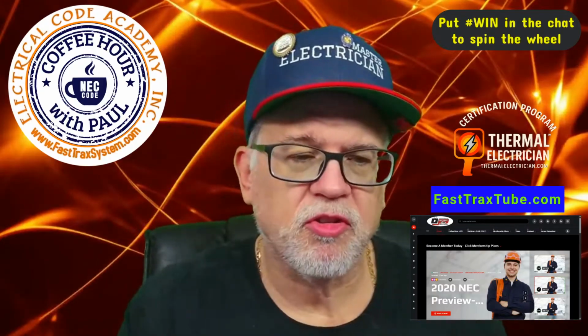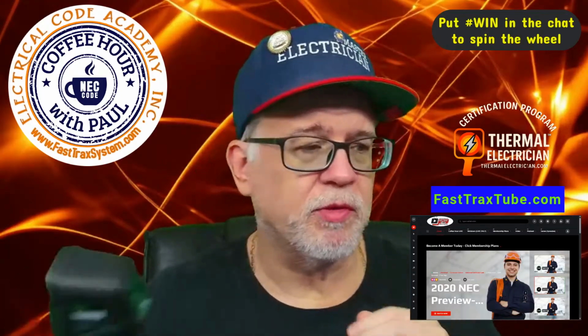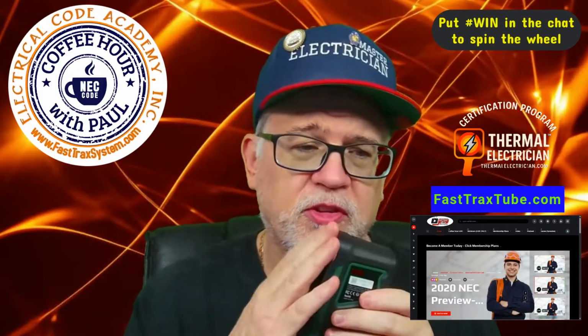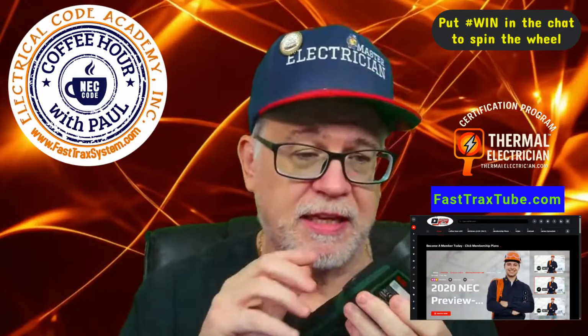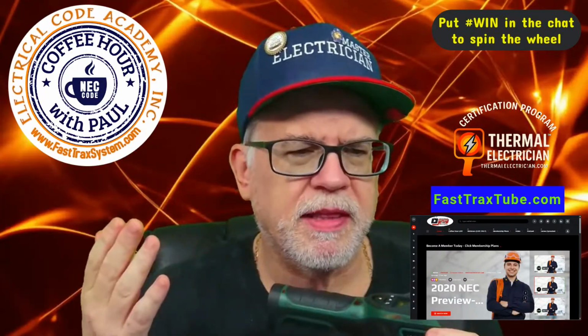But there's certain things that we can do. For example, the emissivity rating that you're going to put in your camera, which is always going to change depending on the surface that you're using. And with these cameras, it's real easy. Just click, click, click. You do it on the go. Most cameras are going to be that way.